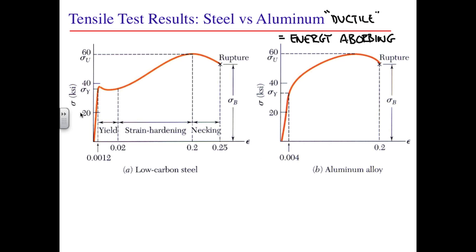A material that absorbs relatively little energy before breaking is a brittle material. A glass or ceramic would typically fall into this category. Brittle materials can often take significant load, but then fracture suddenly with little warning as they approach their limit loads. Most of our applications are going to be in structural materials, and we like to avoid brittle failure, so the ductile materials are the most appropriate for us to examine.